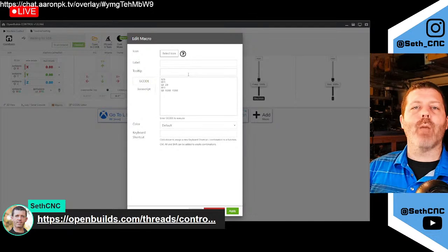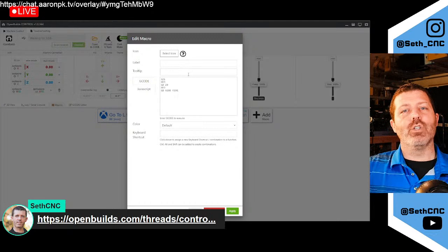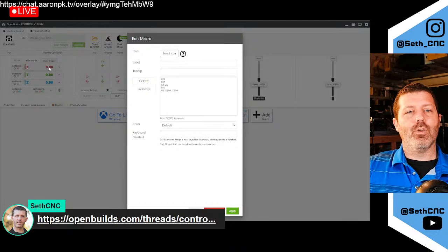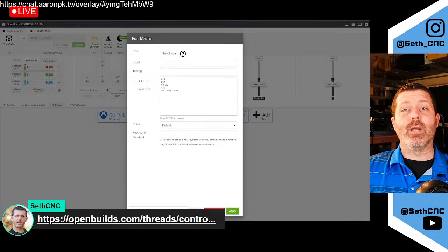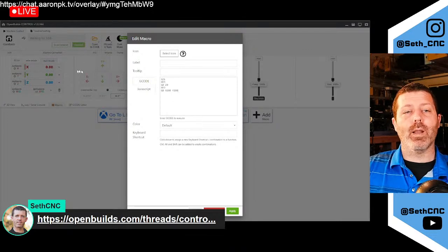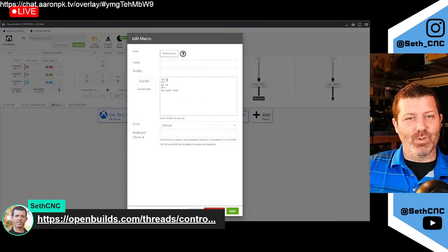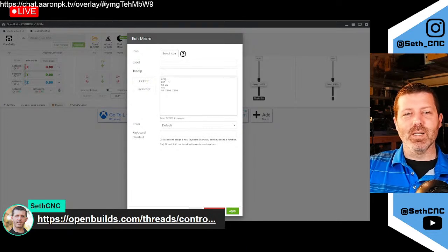So you could test this out by jogging to home the machine and then jog it to a position and say, oh, that's where I want it to park. By jogging it from there, you would have the coordinates up here showing for what you would want to bring in here to get that position, right? So you'd home it, set X and Y zeros over here, and then jog it to where you want it to park, and then pull those numerical values that are showing here and put them in these spots. Currently, I've got it set to inch mode, so you'd have to keep in mind which mode you're in when you pull those numbers to set it in here, right? Does that make sense, you guys? Let me know if I've lost anybody yet on that part.